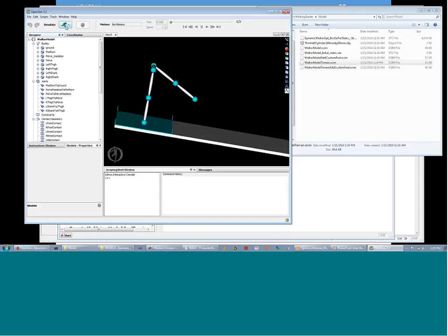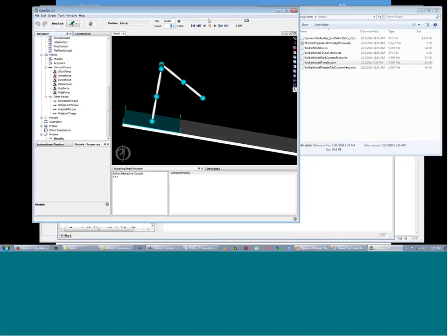So we can actually use this running man. If we click on the arrow, we can change the end time. I've had it set to 2 seconds. And now when we click on the running man, our model simulates and actually moves so quickly we can't see everything that happened. On the right side of the top menu are the movie control tools, and we can change the replay speed. In this case, I'm going to set it to 1/4 and then run our model.